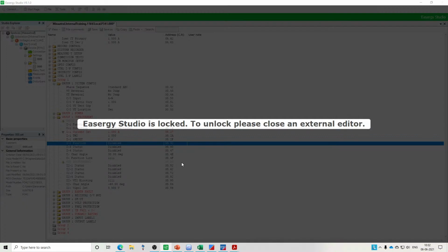This is something that I feel a lot of protection engineers will find very easy to use. Because there is not much logic involved, you just need to connect a particular protection function to its own particular inputs or outputs, give the settings as per your recommendations, and set your analog inputs configuration, right?